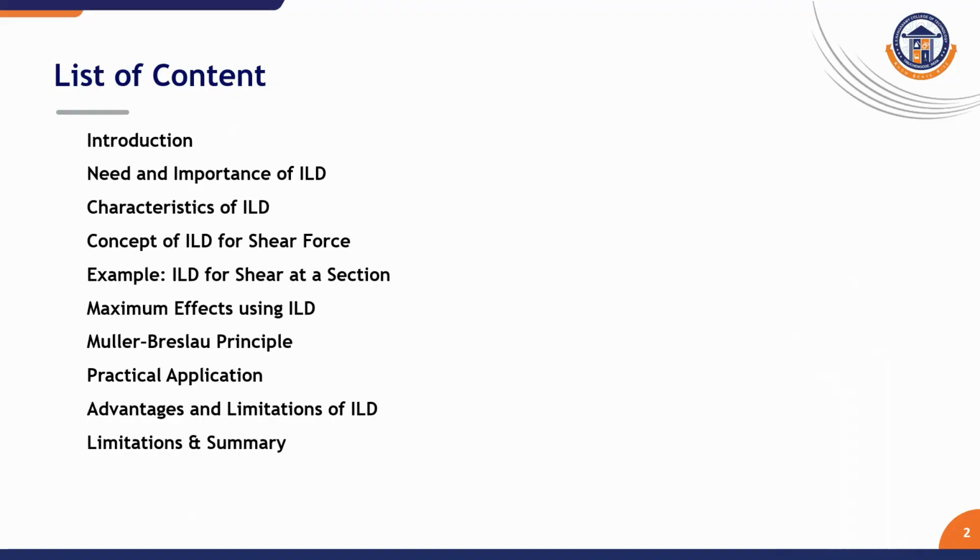We will then focus on the concepts of ILD for shear force, breaking down its construction and interpretations. Practical examples will be provided to illustrate the process for specific sections. We will learn how to determine maximum effects with these diagrams. The powerful Müller-Breslau principle for indeterminate structures will be introduced, and we will explore practical applications across various engineering domains. Finally, we will conclude with a balanced assessment of the advantages and limitations of this method, leading to a summary.